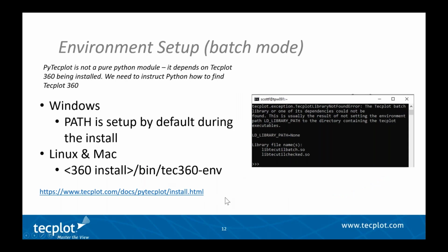So there can be some little gotchas with the Python installation, because this is not a pure Python module. This is a Python module that actually requires the binaries that come with Tecplot 360. So it requires Tecplot 360 be installed on your machine as well. And because we are utilizing libraries which are installed with Tecplot 360, Python needs to know where to find them.